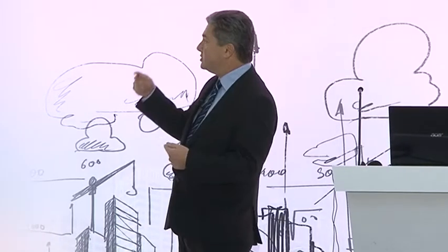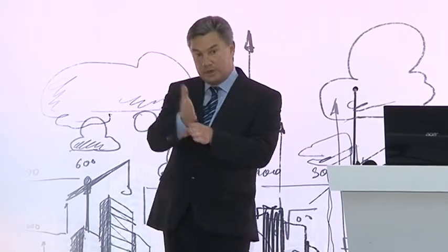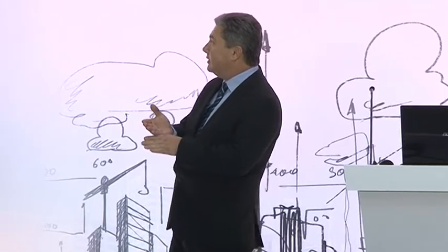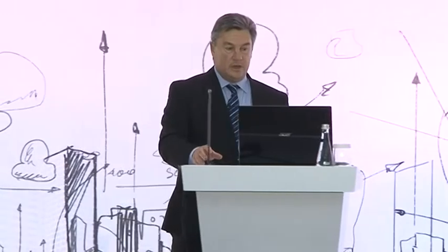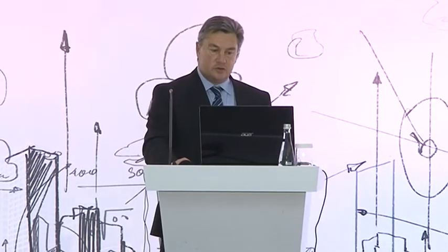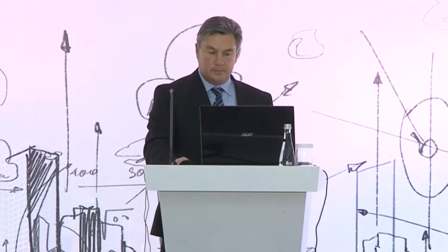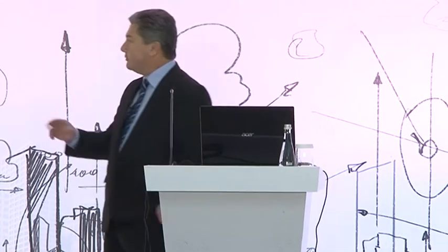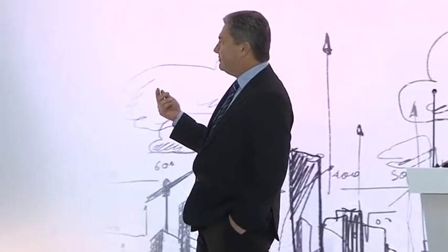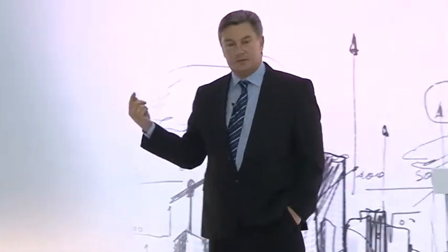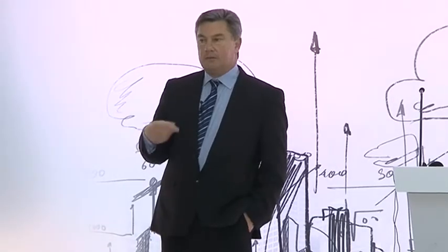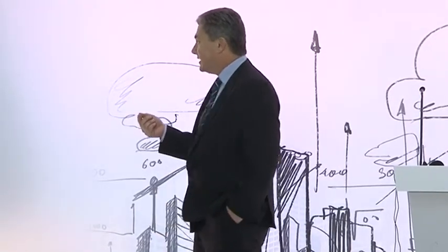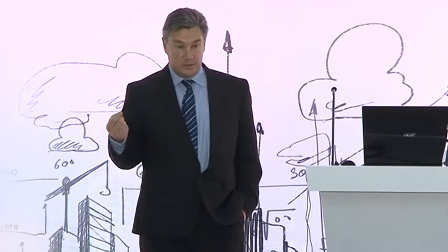If you do that, it will respect those weightings, so the curve would go up steeper if there was more weight to that activity. So some more interesting things now. We can draw some dynamic status on. So as I move my mouse up the curve, it's giving me dynamic feedback about what percent complete I should be at a particular date, how much it's predicted that I'm going to be slipping at a particular date, and how much work I have done at a particular date.